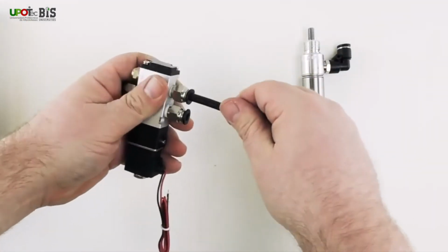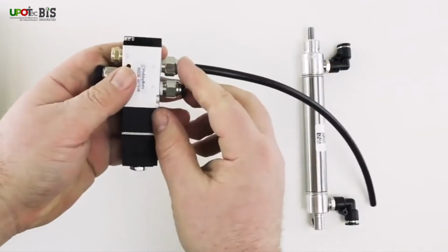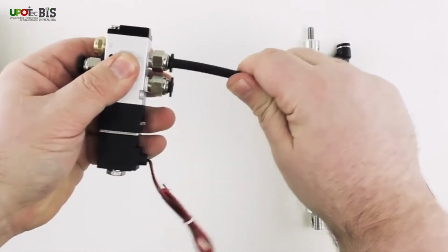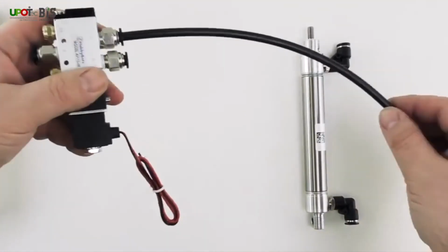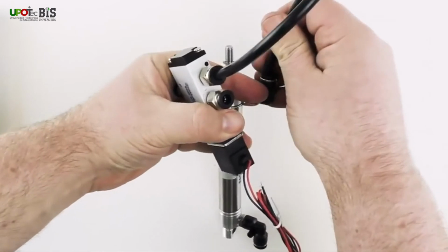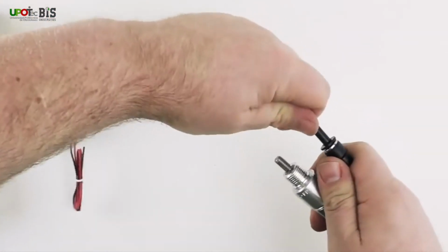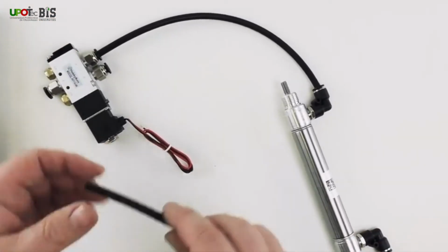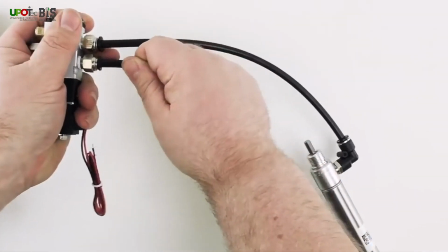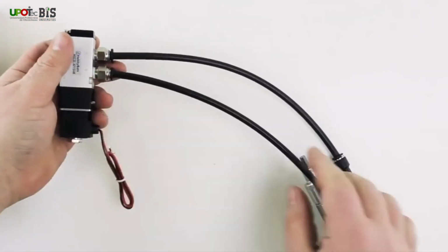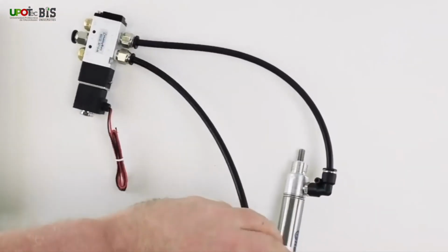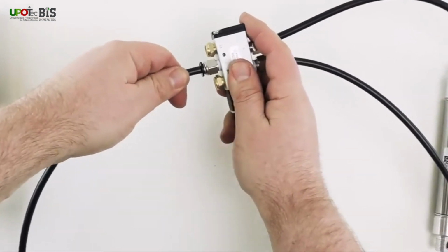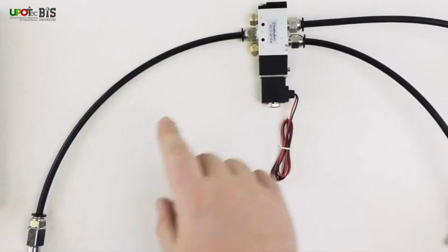We're going to take one of the pieces, insert it into the first of the 2 fittings. You just press it in firmly until you feel it slightly depress into the fitting. You should be able to tug on it and not be able to pull it out. And port A we're going to be putting into the top port of our cylinder. Alright, now we're going to go ahead and take the second piece of air line, plug that into the fitting that's coming out of port B, and plug that into the bottom port of our cylinder. Input of the solenoid.